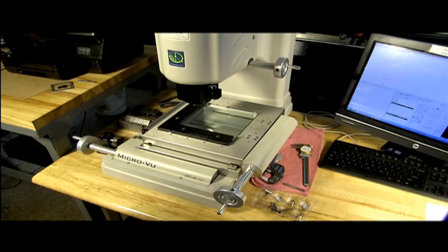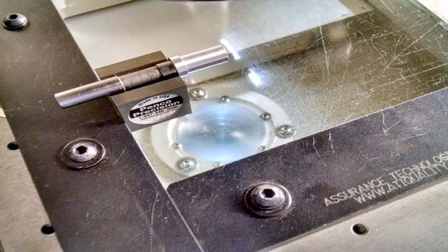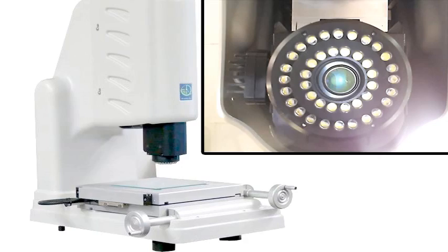Newer comparators, called vision systems, use a video camera and are connected to a computer to control the adjustments of the unit. A light source below the glass plate shines up to the camera in the head above, which sees the feature on the workpiece to be measured. A group of LEDs surround the lens of the camera above the plate. The number of LEDs will vary depending upon the model of the vision system.